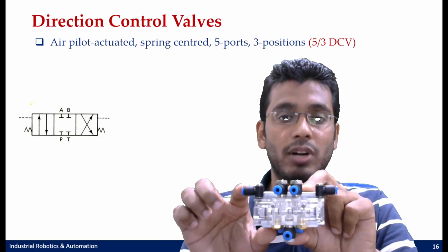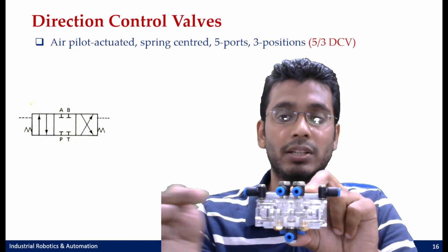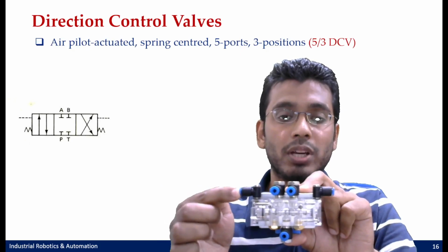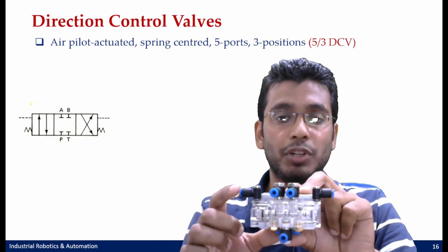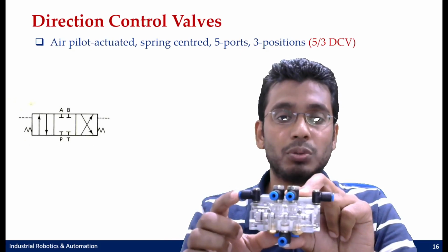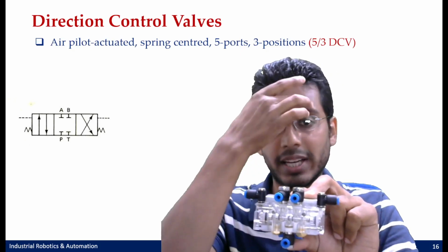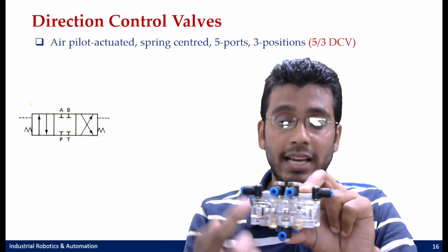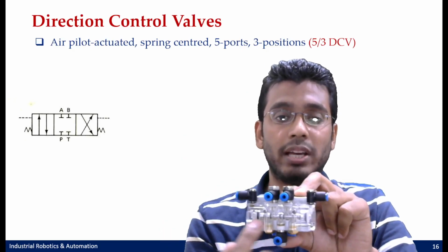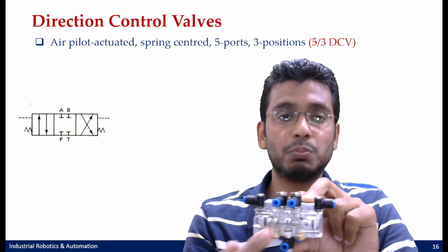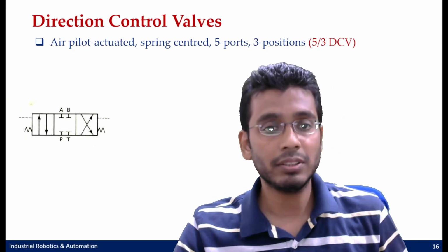In case of a hydraulic system, this would be connected to your pressurized oil line for shifting the spool. And in case of a pneumatic system, this is connected to pressurized gas, that is compressed gas, so that this pressurized line helps in shifting the spool.